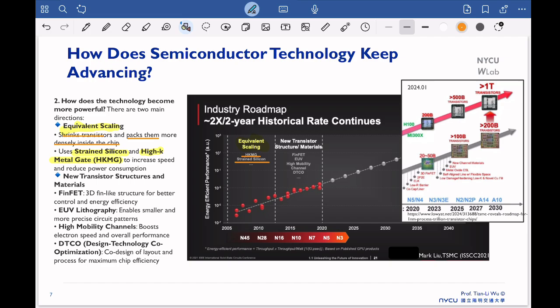2012. And then, of course, each technology, for the strained silicon and for the high-K metal gate, from the research in the lab till the product that we use, takes like 10 years of study. The ideas come out in the lab, then we do some prototypes and then move on to manufacturing. After manufacturing, we also need to make sure that we reach the yield quality. We want to have a good yield. So it always takes time, more than 10 years for this development.